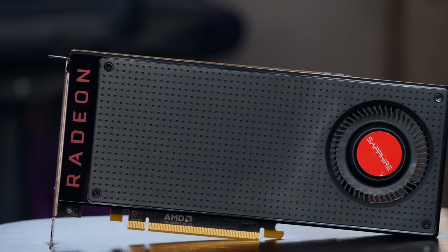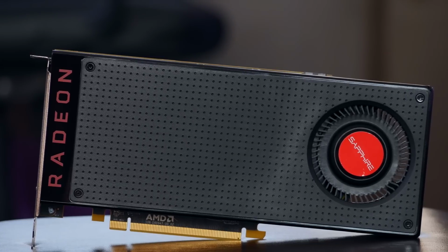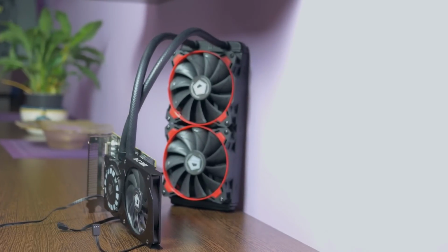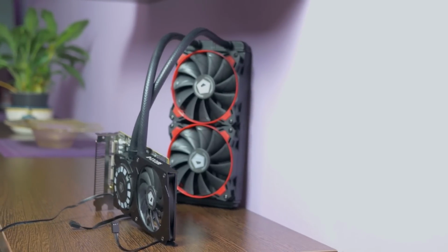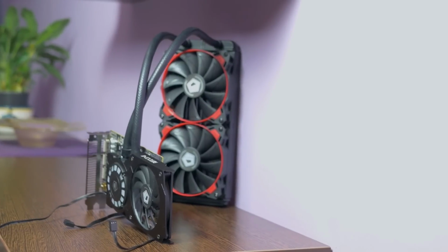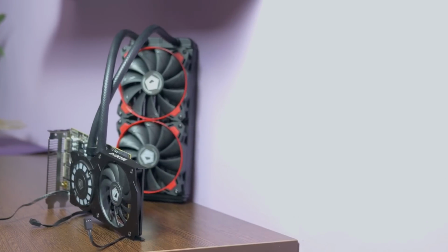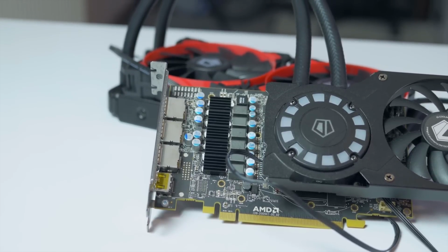When I got the Sapphire reference RX 480, it was because I was tired of waiting for AIB cards availability and decided to make my own card. Most of you might know this contraption. It's running an AIO liquid cooler from ID Cooling called the FrostFlow 240G. With this baby I managed to get a very cool and quiet card. Granted, I did have to use 7 volts for the fans instead of 12 volts for that extra quietness, but this made me lose only 2 Celsius during load.